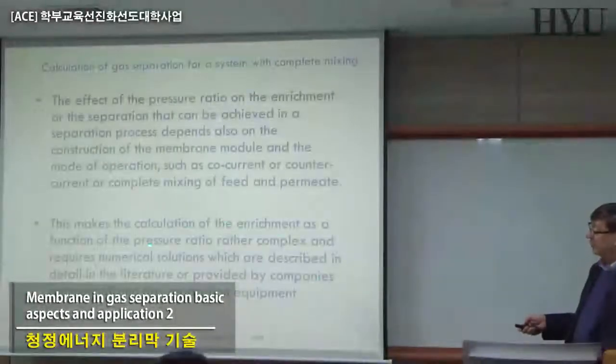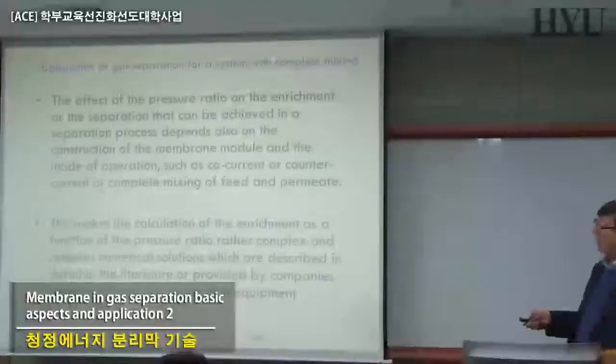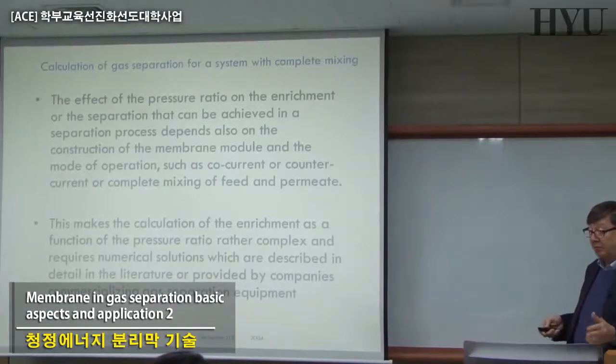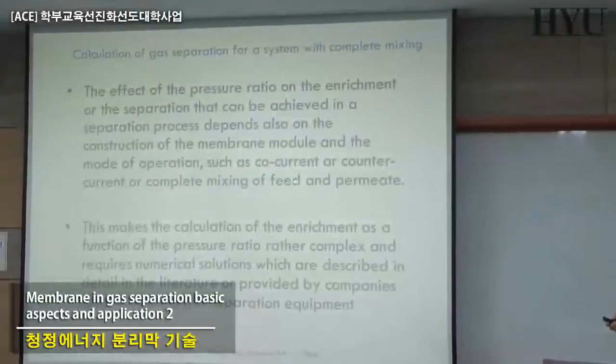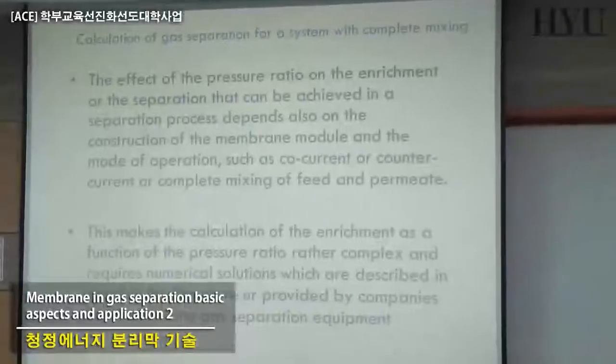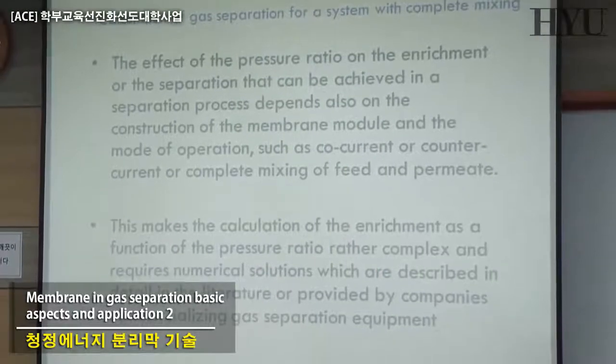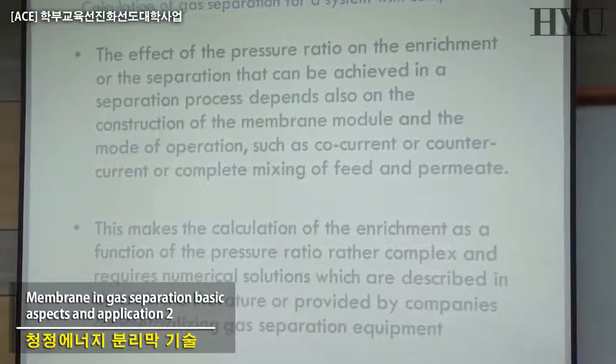To the point that, as you can see here, the calculation that you have to introduce for deciding how to combine your membranes, and for example, not only a cascade of one kind or a cascade of the other kind, but working co-current, working counter-current, that means changing the driving force that controls the transmembrane pressure in the system, can have a significant effect on the overall performance of the system you have.